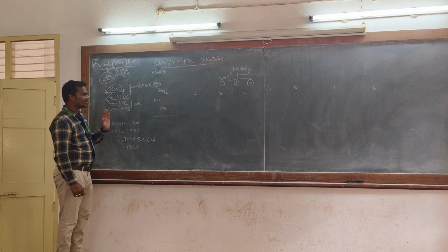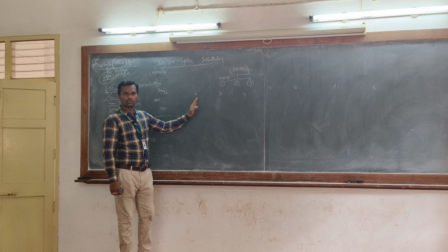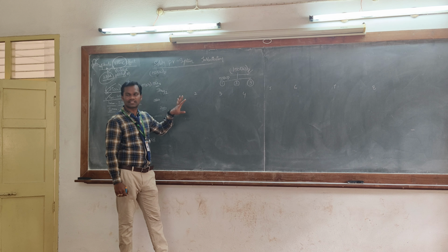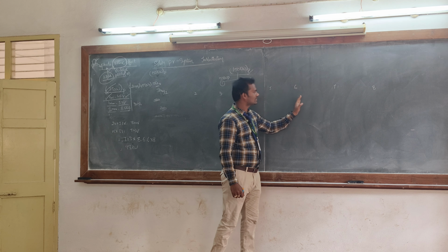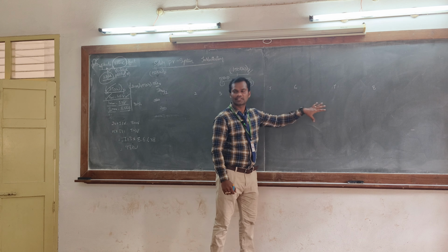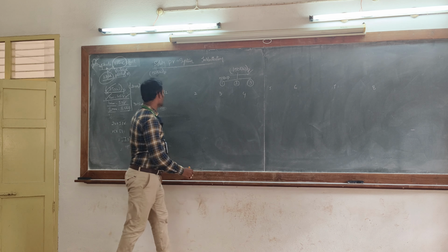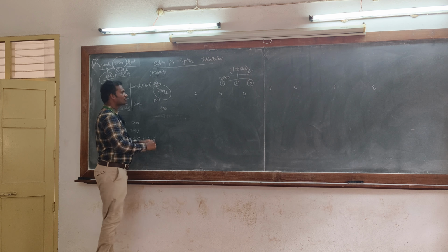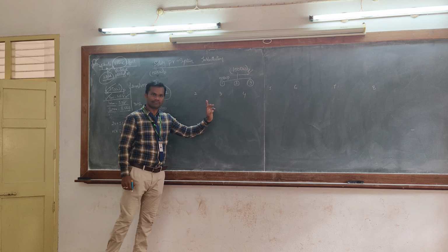Now we are going to create groups of solar panels: group 1, group 2, group 3 and group 4. These four we are taking as one string, and the next groups 5, 6, 7, 8 as the second group of solar panels. Like this, you are going to have string 1, string 2, string 3 and string 4.